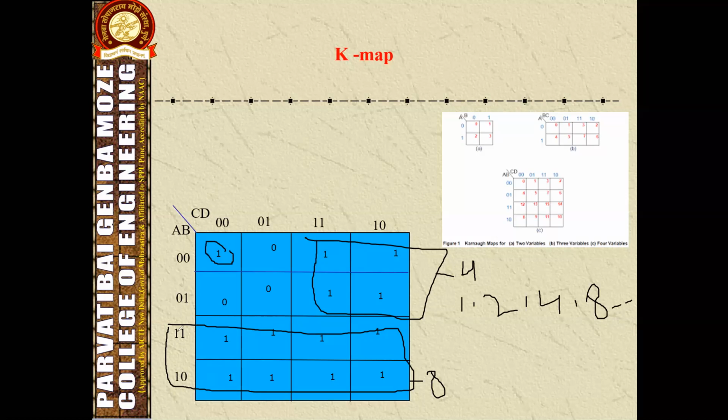So we cannot consider the common characteristic. So sorry, we can consider the common characteristic here. So the value A, which is having high and high, both the rows having common value A. So this group gives the value A, and let's see what value this group will give here. So both the rows, these two rows are grouped here. So what is the common value in these two rows? It is A bar. So this group gives A bar, and these two groups are engaged here.